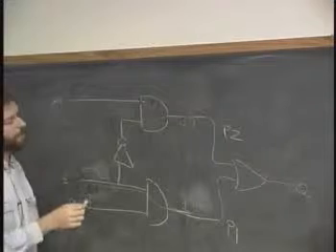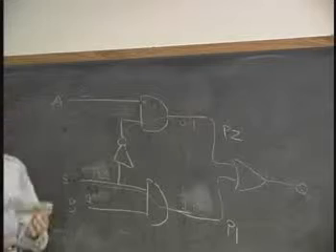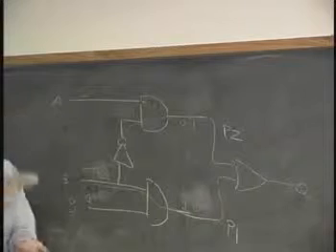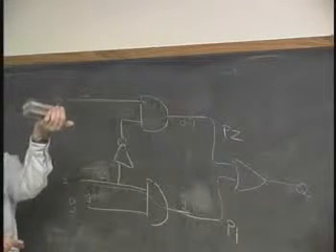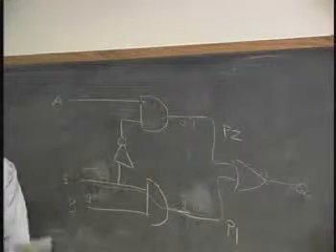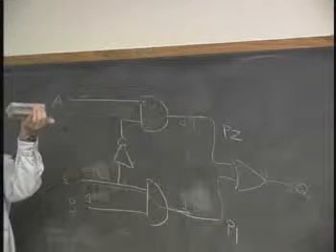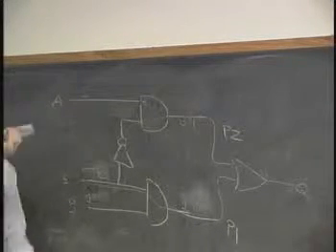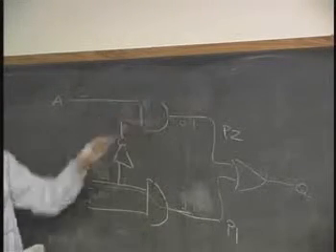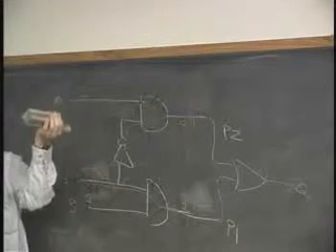And so if I think about this as kind of P1 and P2, let's think of this eraser as the OR gate. Okay? If P1 is high, the OR gate is high. If P2 is high, and I do this right, the OR gate is high. Or if both of them are high, the OR gate is high. And if both of them are low, the OR gate's low. Well, the trouble is that here we are with P1, and P1's going to drop off, and then P2 is going to pick up. And during that small period of time, when we switch from this one being in charge to this one being in charge, what's going to happen to the output? It's going to have a little glitch going down.